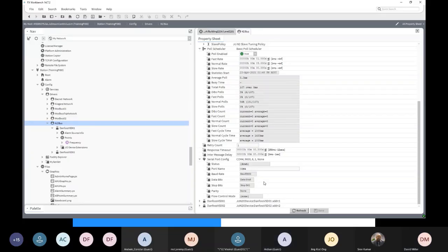So you can set up a network of Modbus meters. You can read the meter values. You can set up a trend on those values to sample them every day, and you can collect all that data. But it's just like a normal BMS, you've got all that data. If you want to actually do something with that data, then it comes down to what do they mean when they say billing system?